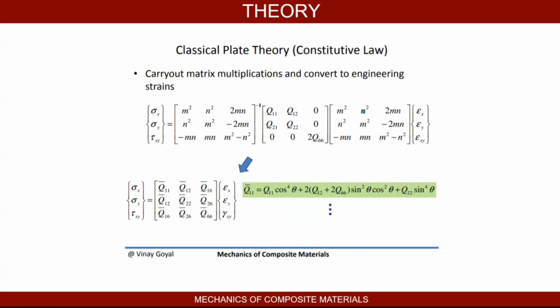So as I referred to before, those are in the global coordinate system. And as we know, and as we saw from the layup, each layer of lamina is at a different angle. So to find the effective stiffness matrix, you will need to perform a transformation from the Q matrix using the relationships that we reviewed above by using a transformation matrix.